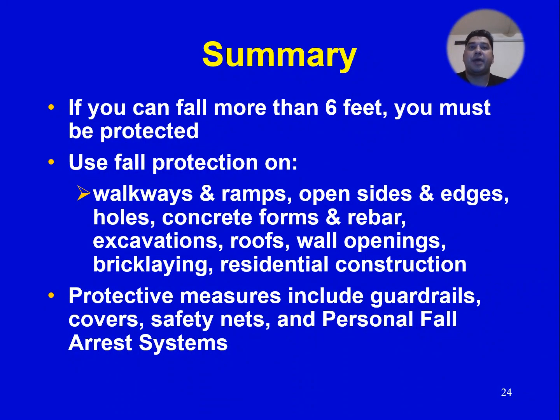Now let's summarize what we have learned so far. If you can fall more than 6 feet, you must be protected. Use fall protection on walkways and ramps, open sides and edges, holes, concrete forms and rebar, excavations, roofs, wall openings, bricklaying, residential construction. Protective measures include guardrails, covers, safety nets, and personal fall arrest systems. So these are the things which we have learned so far, and that's all from today's training.